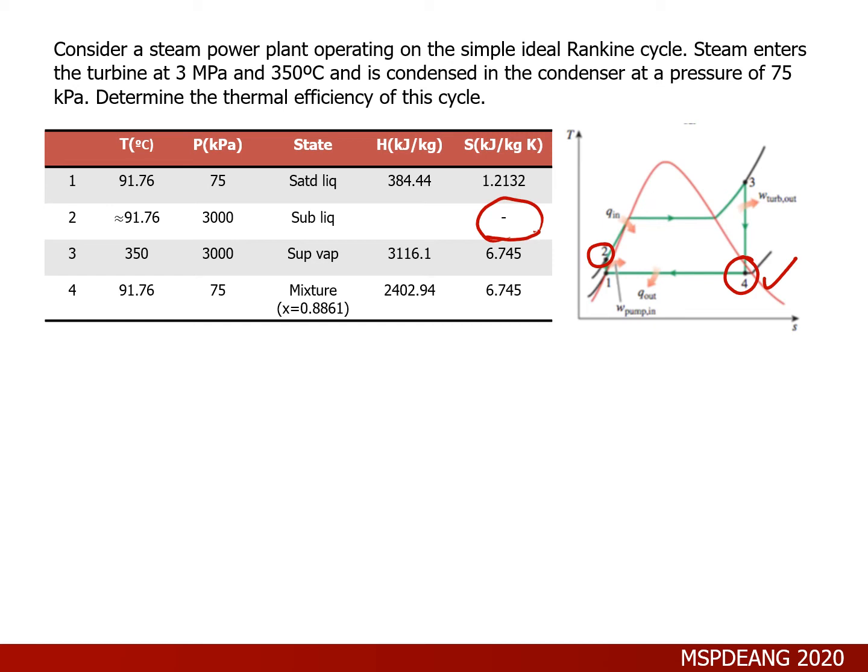However, we won't be doing that, because we have already approximated the enthalpy change, so our approximation for entropy change will not be good. We approximate the enthalpy change for pumps to be a function of the pressure change only, because the temperature change for pumps is not appreciable, which is actually observed in real life as well.